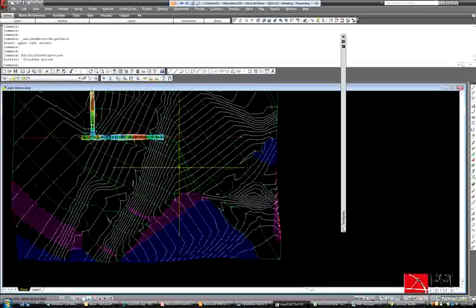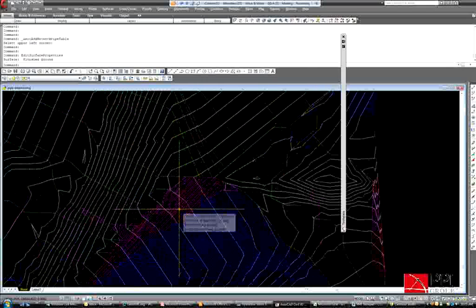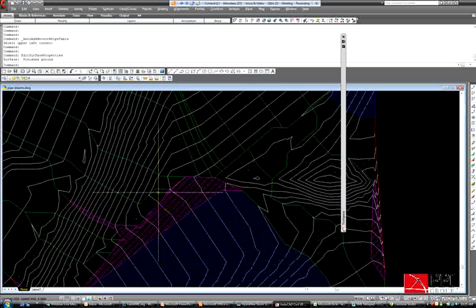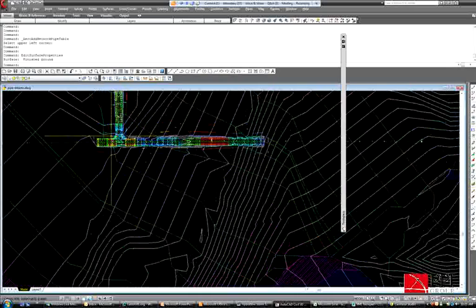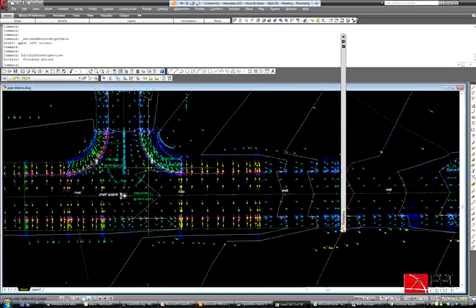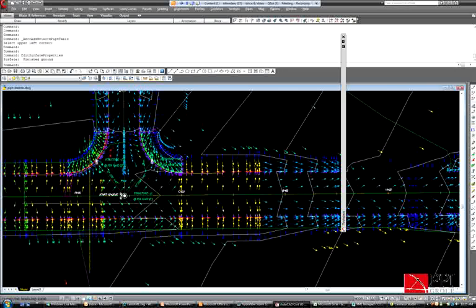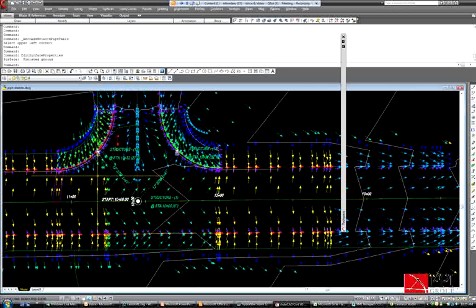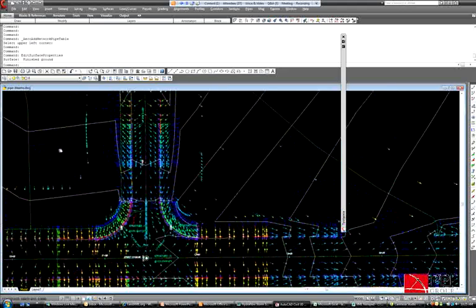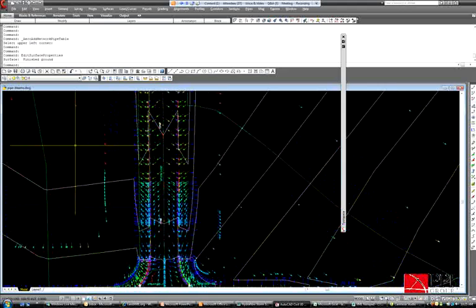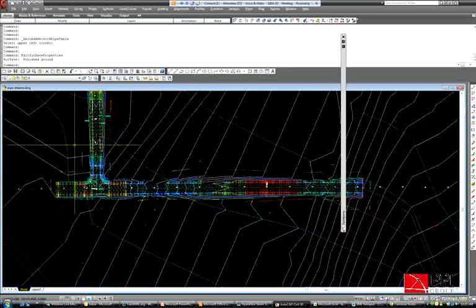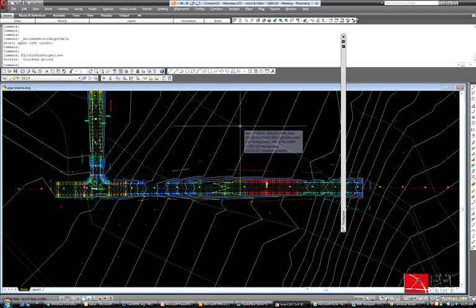And all this coloring and banding, you can change that within the style, obviously, the display of the style. One of my favorite tools for design, and it works really well for road design, it's how I placed my catch basins in here, and particularly in parking lot design. It's a good tool, these slope arrows, and like anything else, you can affect the color. The colors have to do with the grade, obviously. And so here we've got our watersheds turned on in here as well.